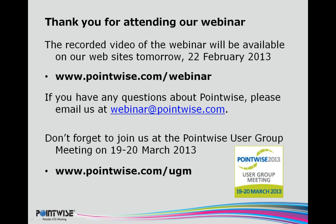And if you'll recall, Pointwise is actually the package between the two that reads in the other's files. So when you're transferring data back and forth, Pointwise will read in GridGen's files and it will write GridGen's files, .gg and DBA files. But it does not transfer project files into GridGen. GridGen cannot read project files.